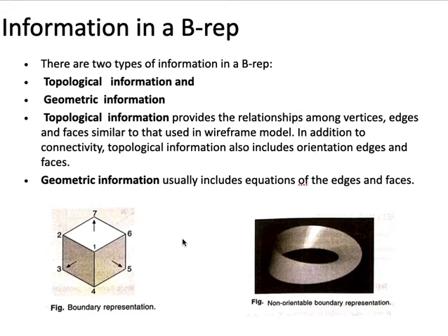If that face is given by an equation, the equation must be rewritten so that the normal vector at every point on the part that is being used as the face points to the exterior of the solid. Therefore, by inspecting normal vectors, one can immediately tell the inside and outside of the solid under B-rep. This orientation must be done for all the faces.